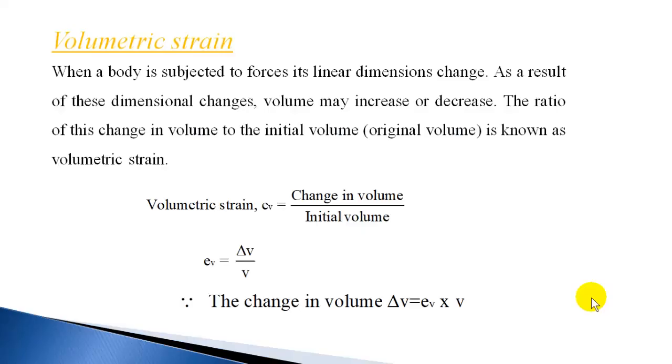In today's class, I'll explain the volumetric strain induced in a body due to applied forces. All of you know this linear strain induced when forces act. When forces act on a body, its linear dimensions change. If it is acting in the x direction, the dimension in the x direction will change. Simultaneously, it also induces strains in the lateral dimensions, that is y and z directions.